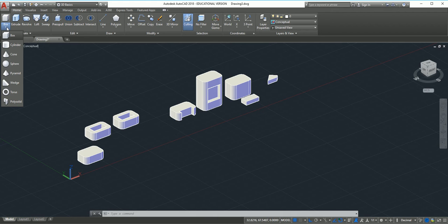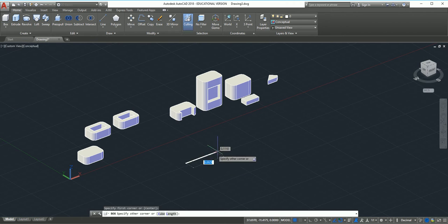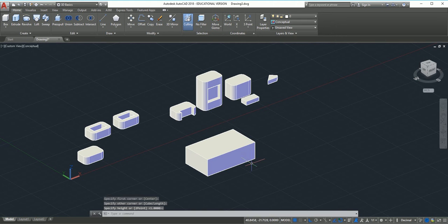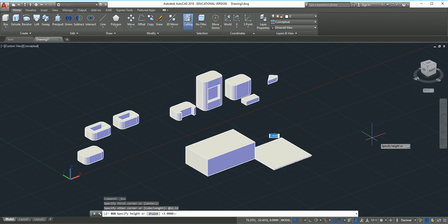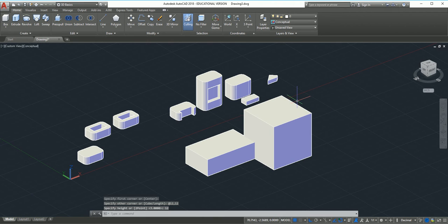We're going to move back kind of to the beginning, but I just want to show you extruding from 2D objects and stuff. All of these shapes are pre-built-in shapes. They're exactly that. They're boxes. If I do a box, I could type in dimensions, and it'll come out of those dimensions. Actually, I think you have to put the @ sign, right? If I do at 12. Yeah. So it's 12 by 12, and then I could hit 12. So it's a 12 by 12 by 12 cube.